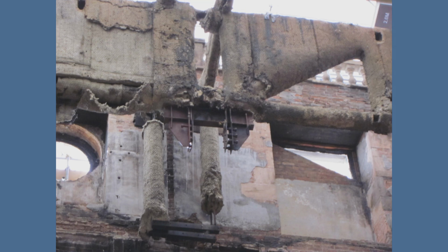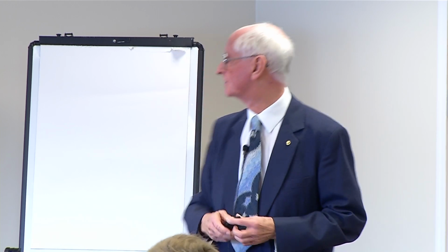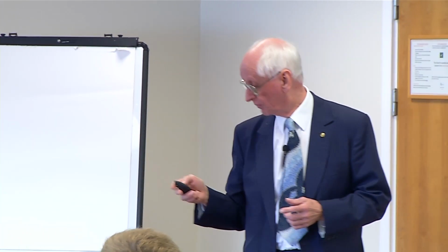These bolts here are actually clamping bolts which clamp the plates onto the side of the timber. So they don't actually go into the timber itself. But that is highly suspect, having been subjected to such high temperatures in the fire. But the small fixings are really important.